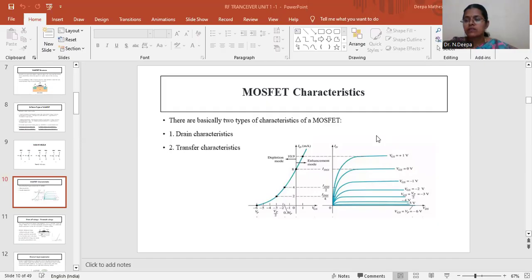In this we can see that with increasing voltage, the current flowing through the terminals increases. You can see this in the graph. A voltage more than the threshold voltage is the condition for current to flow. There are three regions available in these characteristics. The first one is the saturation region, in which the drain current is constant. Another one is the cutoff region. When it cannot achieve the threshold voltage, the MOSFET remains off.